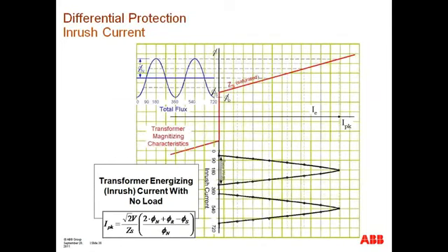But the principle and the basic concern is, as described, you're going to have current that flows through the winding that's associated with the source. There's not going to be any current flowing through the winding that's effectively connected through the load, and that's effectively seen by the relay as a differential condition. And that's a very practical explanation.